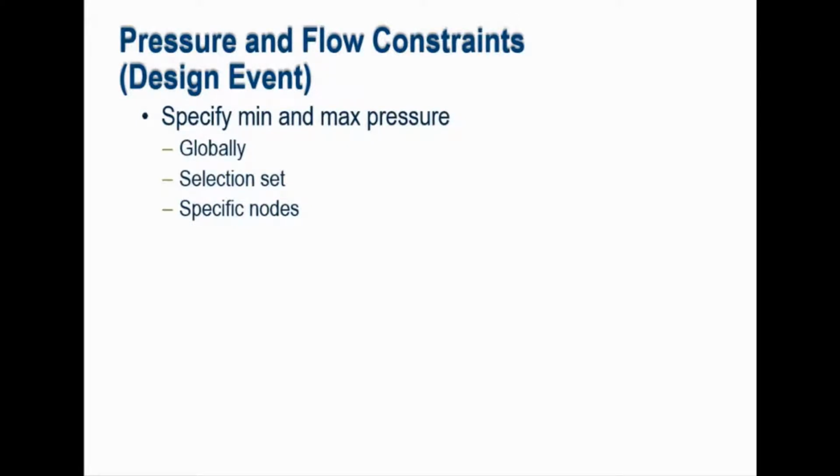So you could elect to put that for that particular node set. Maximum pressure, it's usually not a problem, but sometimes you may want to have this model indicate if it is. If you don't want maximum pressure to be considered, set it to be a high value. The default is going to be 200 psi.